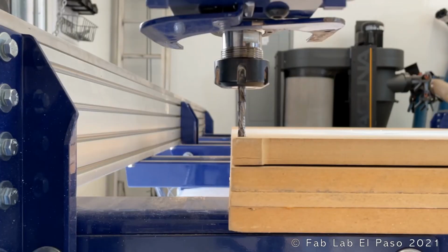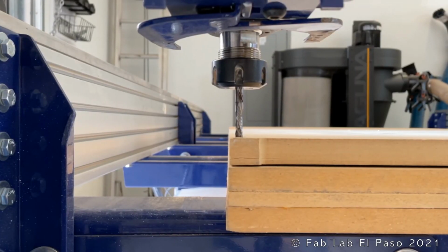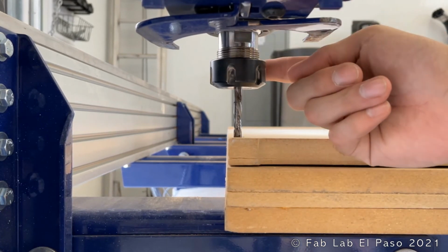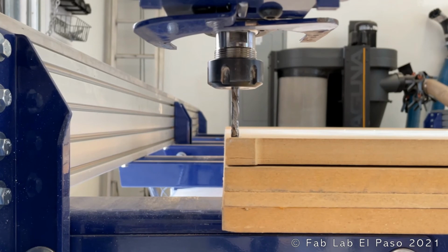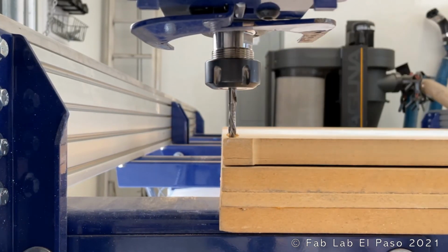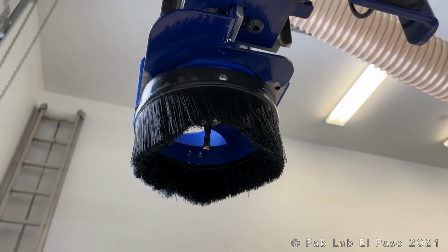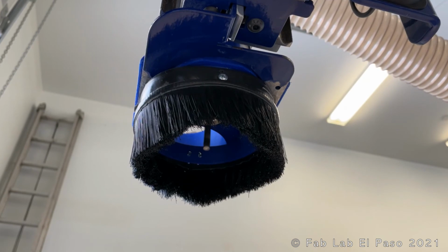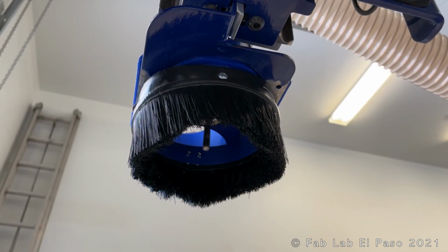We also specified 0 on top of material, so I'll locate my tool over this section on top of the material, and that's the area that I'll use later when I have to re-zero with other tools. Then, in the same manner, I manually hit 0 Z-axis. I'll run a spindle warm-up routine, and after it's done, which is about 5 minutes, we will be ready to start.